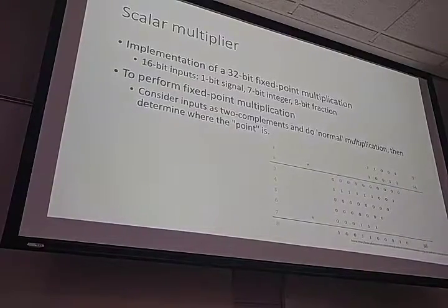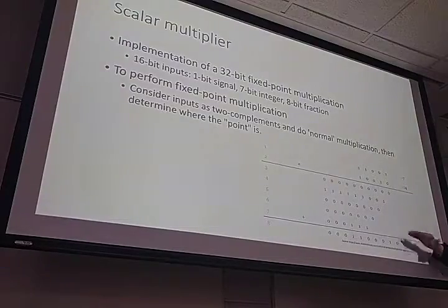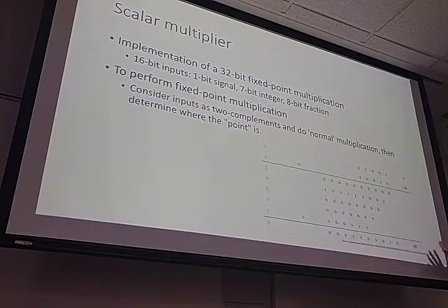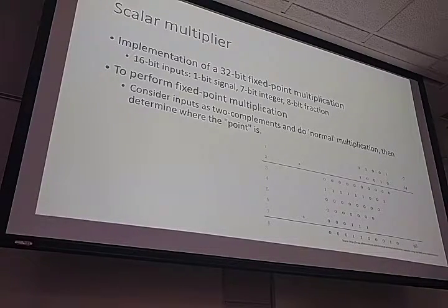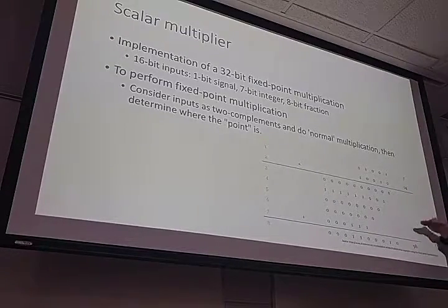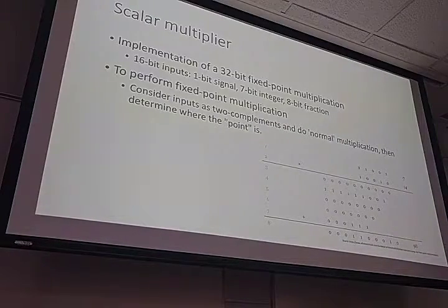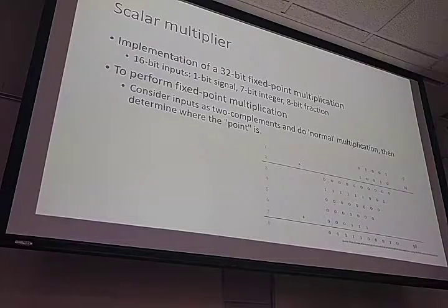So by the end of the day, you need to accumulate all these parcels, and you can do this in two ways, or more than two ways actually. If you use just resources like LUTs and registers, you need to generate one of these parcels on each clock cycle and accumulate, which would introduce a lot of latency.